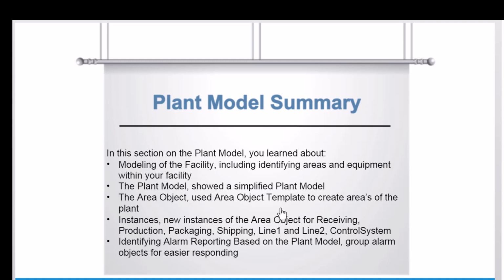Identifying alarm reporting based on the plant model. We learned we should group alarm objects in the same area for easier responding for the operator responsible for those alarms. Now, you're ready to move to the next section that covers the deployment model. However, first, here are a few knowledge check questions for you to answer.